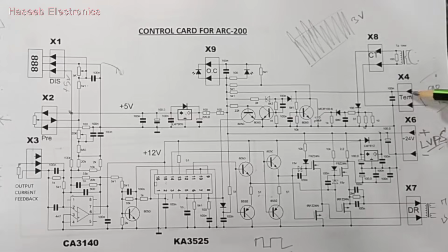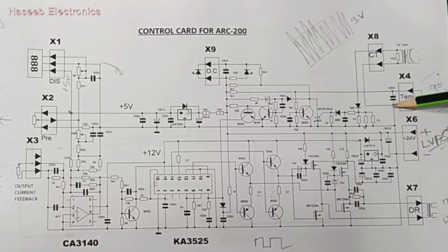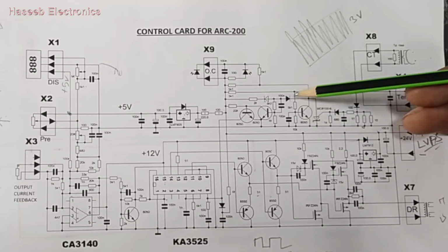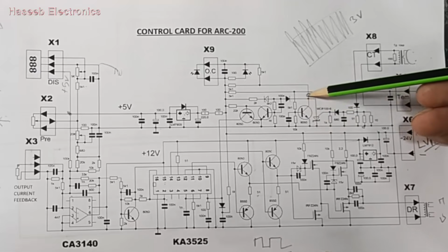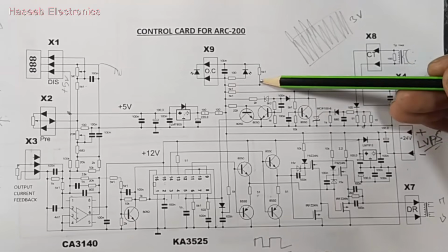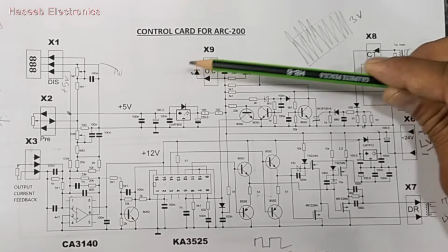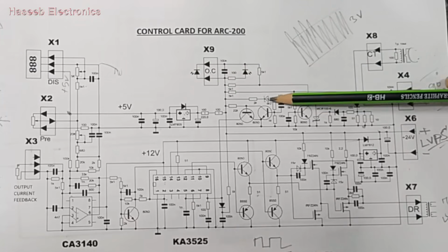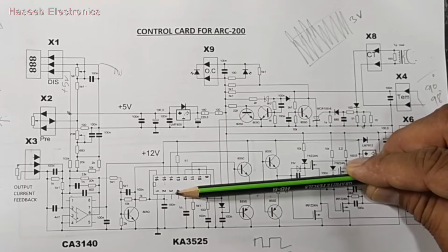When it switches, it will give a signal to this transistor, and at the same time it will pass a signal here. This transistor will switch, this ground voltage will switch, and this path will turn on, this LED will be on, OC light will be on, and this transistor will be triggered so that the IC will turn off.